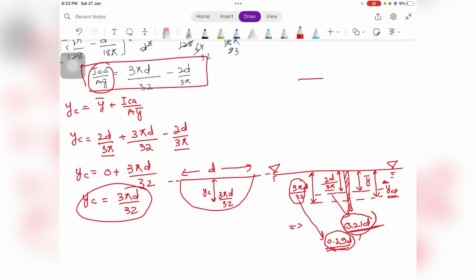All right, so this was our plate, and we can safely assume that the distribution of the hydrostatic pressure is something like this. All right. So the force on this semicircular plate is concentrated a little below the CG.